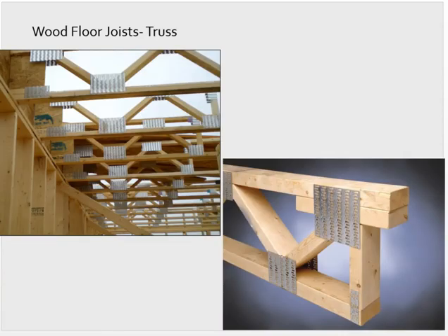Alright, and then finally trusses. So this is made up of 2x dimensional lumber, typically 2x4s, sometimes 2x6s. So again, we have a top chord, bottom chord, the triangles or triangulated panels in the middle, and those are put together with a hydraulic press that fastens these gusset plates. And these should never be cut.